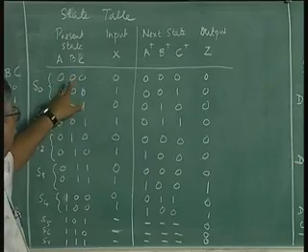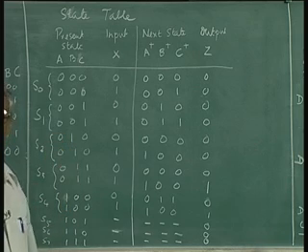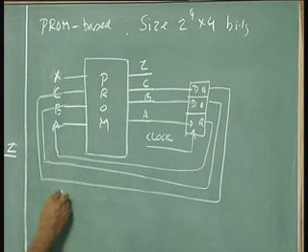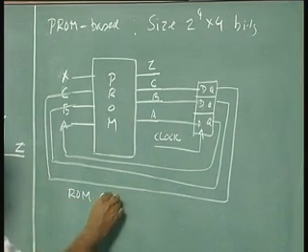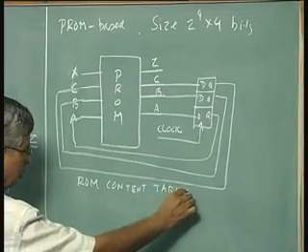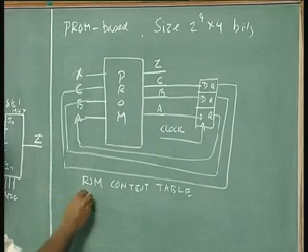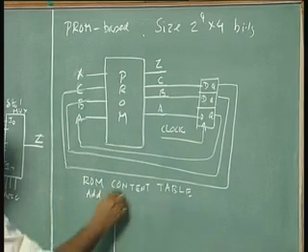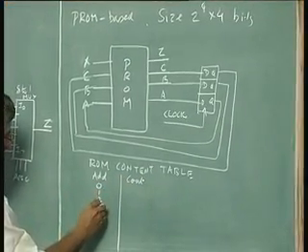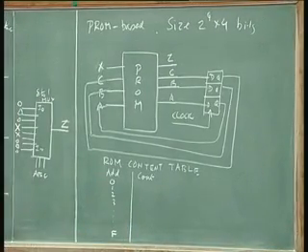So, present state, the first address is 0, which I told you is generally written in hexadecimal. So, the PROM table, or the ROM content table as they call it for this exercise, will be address and content, both in hexadecimal. I can write 0, 1, 2, 3, there is no need to write more, because it goes from 0 to F.